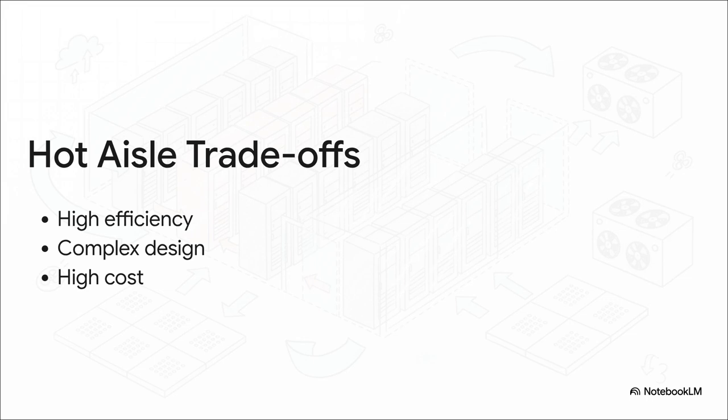The pros and cons shift dramatically here. Pros: higher energy efficiency, better high-density performance, and improved cooling operation. Cons: complex design and installation, fire suppression coordination is absolutely required, and a higher upfront cost. By managing that return air more effectively, you get incredible performance for modern, high-density setups. But you really have to earn it. You've got higher initial costs, and crucially, you have to carefully coordinate these big physical structures with the building's fire suppression systems, which is a whole other puzzle to solve.